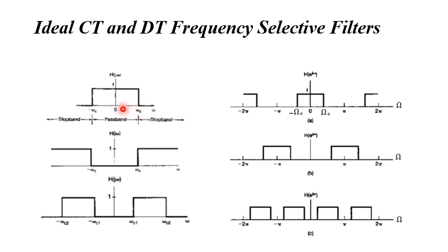Up to this range it passes, and for the negative case also, that is 0 to minus omega c, where omega c is the cutoff frequency of the filter. These responses are the ideal ones. Below the cutoff frequency the signals are passed, and above the cutoff frequency signals are stopped. Similarly for the negative case. So this is an example of the low pass filter.